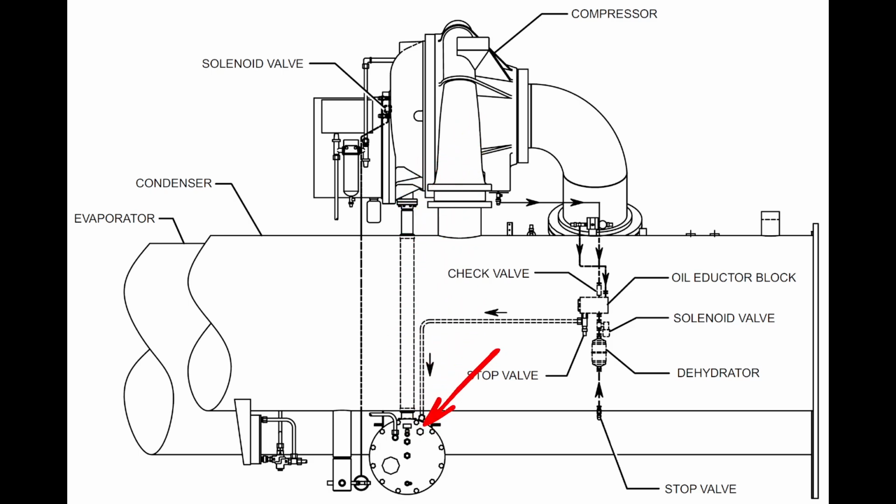But we also have a separate vent line just like we did with the Trane, except it goes up into the compressor, whereas the Trane style returns to the evaporator, at least on the newer machines. So overall, same basic science, same basic flow and structure, all the same things are happening. We're just applying it in a slightly different application.